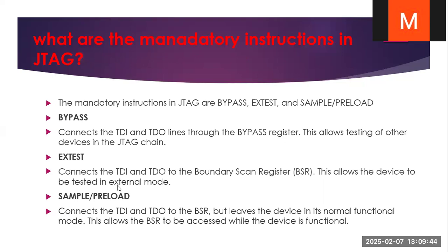This allows the device to be tested in external mode. Sample or preload connects the TDI and TDO to the boundary scan register, but leaves the device in its normal functional mode. This allows the boundary scan register to be accessed while the device is in functional mode.